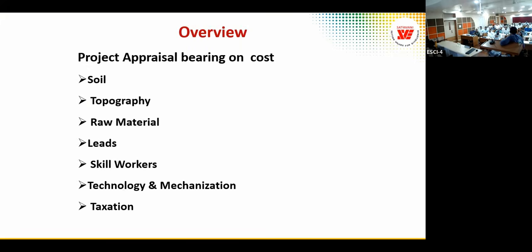Next, soil. As I mentioned, geotechnical investigation is very important. For the soil, we also have spoil tips, that means disposal of excess surplus earth or rock, and borrow pits, that is use of soil from an external location. Also, we have to identify these; that is part of the investigation actually.